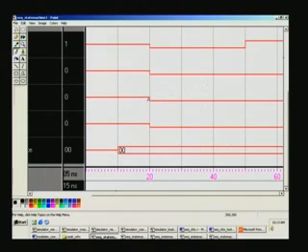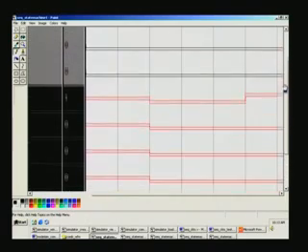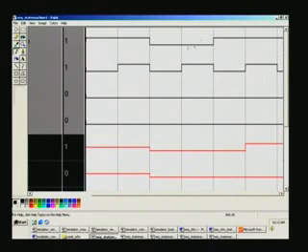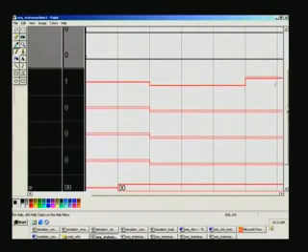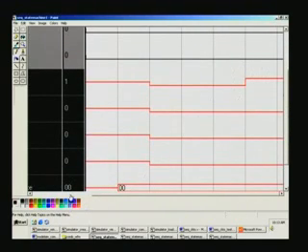There's nothing much to convey except that all the lamps are 0, and at this point of time the real S0 state comes into play, because reset is removed, and following the positive edge of the clock it starts getting activated, and right at that point of time it enters the S0 state and activates Z0 there.